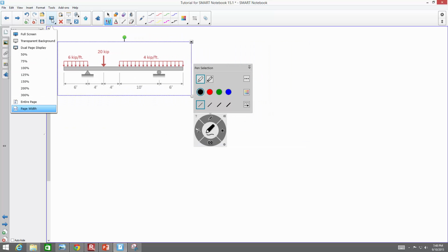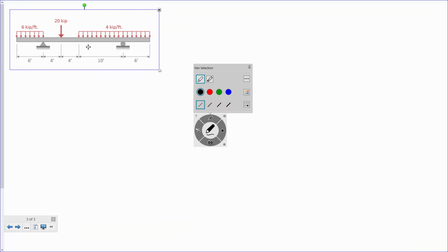Real quick before we get on, you said we're not going to do a statically determinate, but just so I remember, statically determinate would be if you replace the roller with another pin. Yeah. Now, not technically for this problem because all the loads are still vertical, but what if I put another roller on it? That would be statically indeterminate because ultimately we would have more unknowns than we do equations of equilibrium. Remember that we only have 3 equations of equilibrium if we're dealing in 2 dimensions: sum of forces in the x direction, sum of forces in the y direction, and sum of moments. If I give you 4 unknowns, then that becomes indeterminate. Okay? That's a good question.